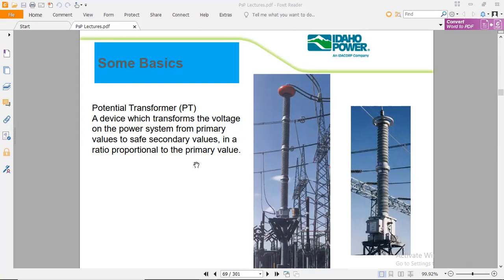We further continue the session with the potential transformer. We mainly understand that it measures the voltage of the outermost power conductor. It is not directly sensing by touching contact of a power line, because there is an enormous amount of voltage like 500 kV, 220 kV, 132 kV, even 66 kV, 11 kV. So it is a kind of transformer which works on the mutual induction principle, not directly through a physical touching contact terminal to measure the potential.